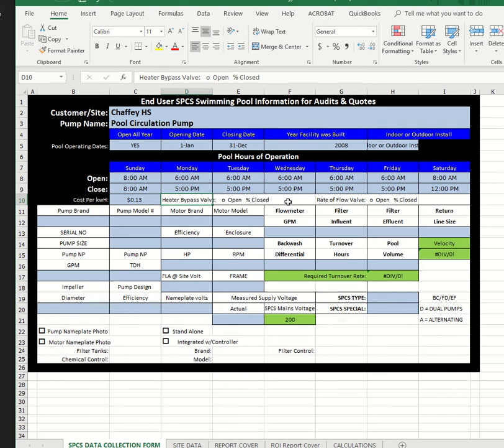We're going to leave this area untouched right now because the valves are probably closed, but we don't know exactly how far. So we have a PACO pump, and it's a 29-5015. Because of the motor frame size and the photographs we took, we know that it is a horizontal split case, and that has a designation from PACO of KP.